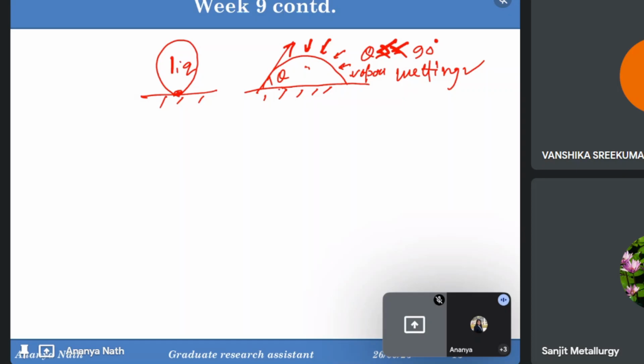But at the same time, metal matrix composite machining is also a big issue, because there are interfacial particles seated over the whole metal. Whenever you try to cut the metal using some tool, the tool easily gets damaged by the cutting of the MMC due to this particle reinforcement. So that is also a big problem.